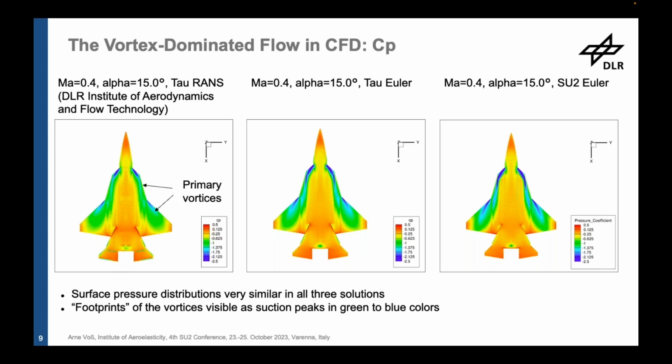Are you simulating the gusts again? Did you use it as a constant or was it more random? I haven't simulated them yet. Well, I started with the help of Pedro at the beginning of this year, and first results are already available. I'm going to show some of them at the ECAS conference this year and the EFAS, the aeroelastic conference in the Netherlands. What I'm going to do is I have 1 - cosine gusts as specified in the certification specifications. Thank you very much. Okay, thank you.